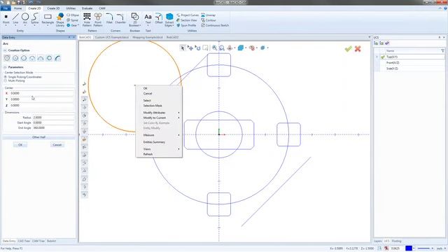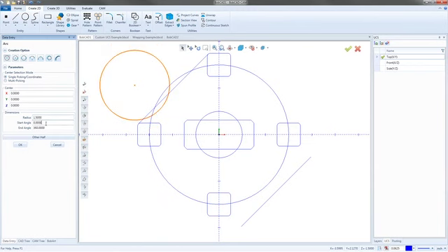All right, cool. So we have our functions. Now, one big thing that they changed was a lot of the sketching functions got a bit bigger. Hold on. Grid 1 inch. Oh, yeah. Okay. So it pretty much gives us a lot more sketch functionality. So right here we have our radius. We can define how large it is. So we just say 1 inch, or let's go 1.5. And that's going to kind of lock it in place. We can tell it exactly where to go.